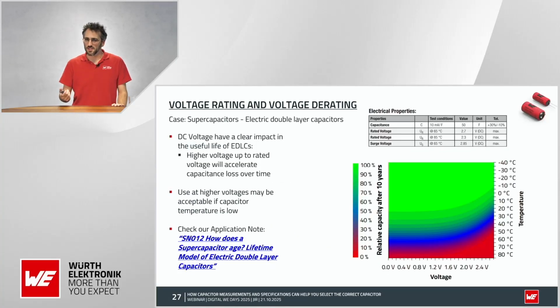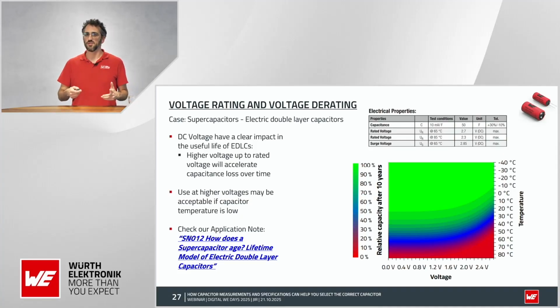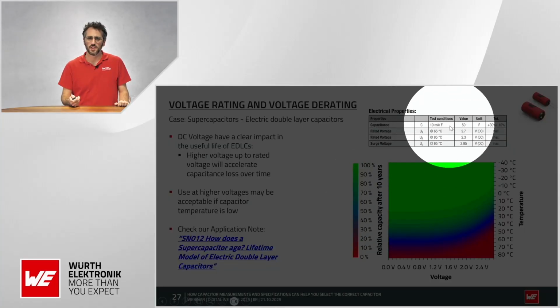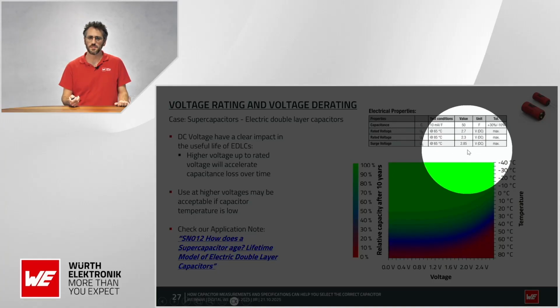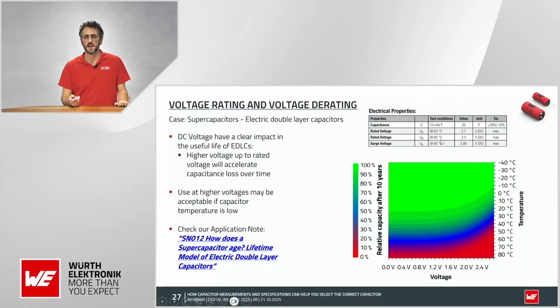So about supercapacitors, I didn't mention this before, but actually it's the opposite. Voltage will actually damage the capacitor, and we have a similar situation as the film. You are allowed to run the capacitors at higher temperature than specified, and the voltage can be reduced if you want to use it at high temperature.